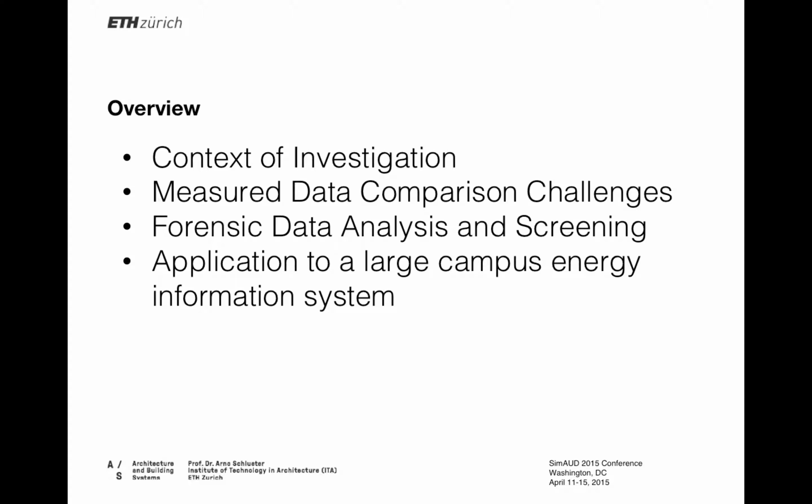In this presentation, I'm going to talk about the context of the investigation in terms of model calibration, urban scale model calibration, and using large raw data sets from sensor systems or energy information systems on a campus. I'm going to talk about a lot of the challenges that go into using that data. I'll talk about a forensic process of data analysis and screening, so multiple layers of analysis that are meant to filter knowledge from the data that help an analyst decide how to use that data for calibration, and then an application to a large data set that I downloaded from the energy information system on campus.